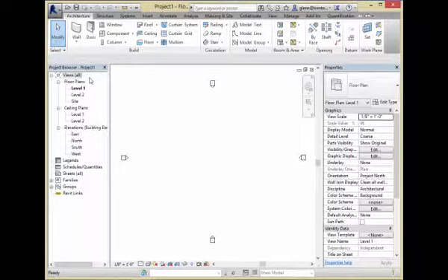In the Starting Point file, I have different floor types. One that's a lot of structural plus some wood finished floor. I have another one which is some wood with carpeting on top, and a third one which is wood with tile on top. Okay, so here's the deal. If you start modeling and laying everything out for a house, what we'll do in the way it's really built is, if you think about the overall interior area, we'll put something down that we'll call the subfloor first and then start building walls on top of it.